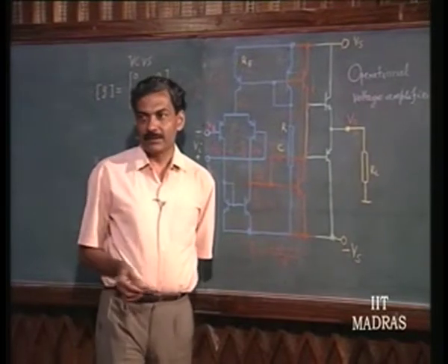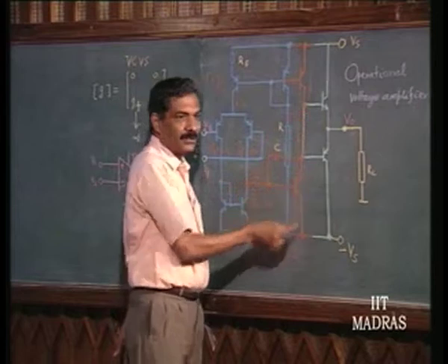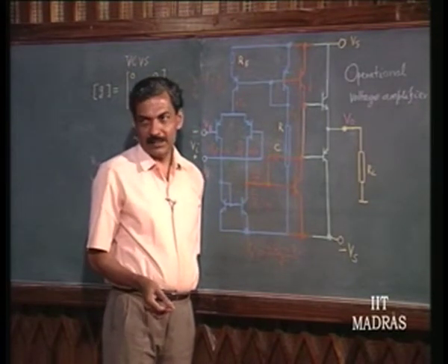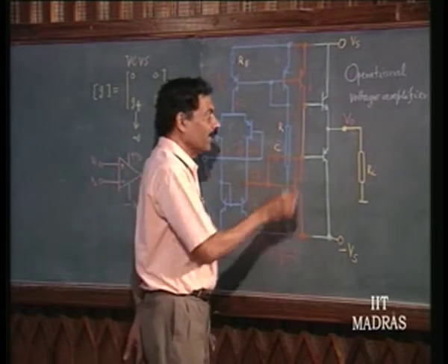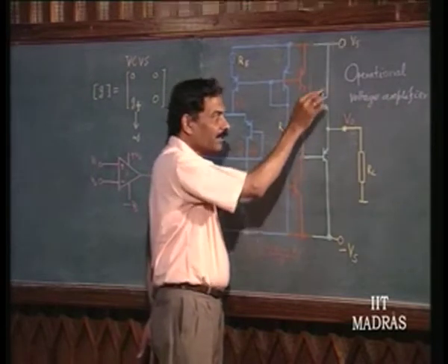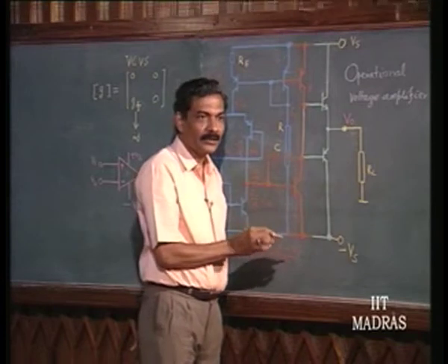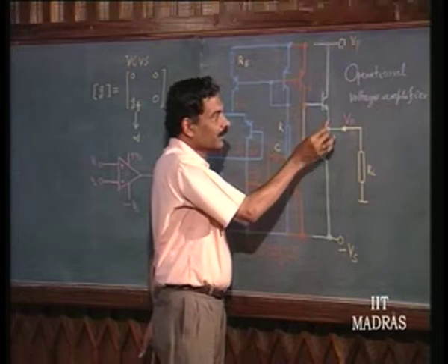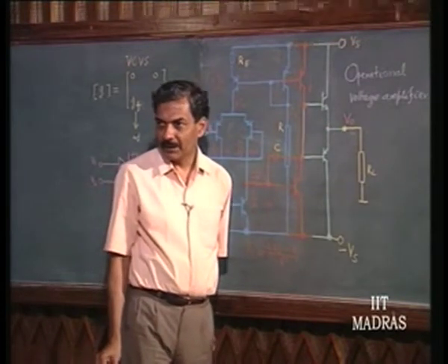Now, this is not very easy, because you are saying this is going to be class B, right. Operating current is 0, okay. So, you have to assume some class AB biasing, that is ultimately we will see that this is not class B at all, it is made class AB. So, there is going to be some amount of current in this, okay. So, you can evaluate the value of RE at that particular point.